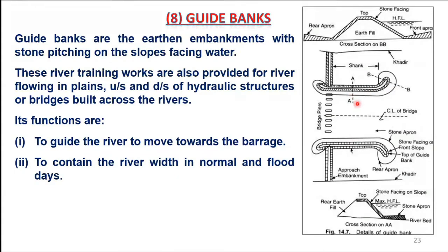This would be the river width, on normal days and even on flood days. In flood days there is too much discharge, but the river width remains the same because we have provided guide banks. These are the two major functions of the guide banks. So its width remains fixed, and then here we provide weirs. That is the guide banks.